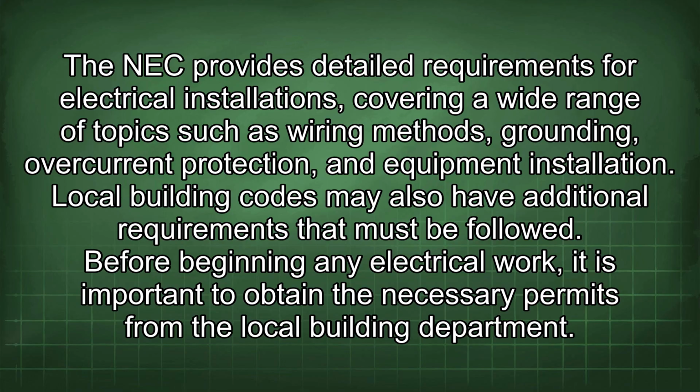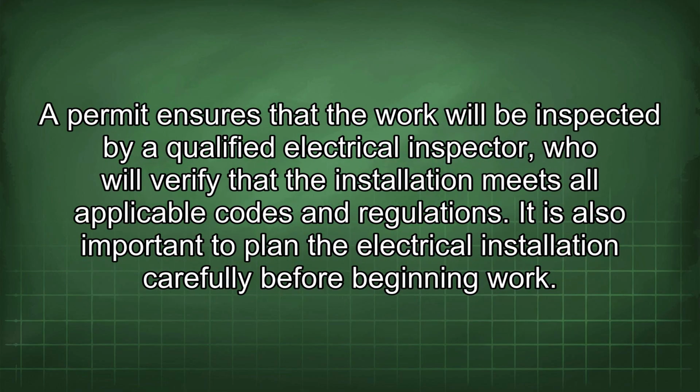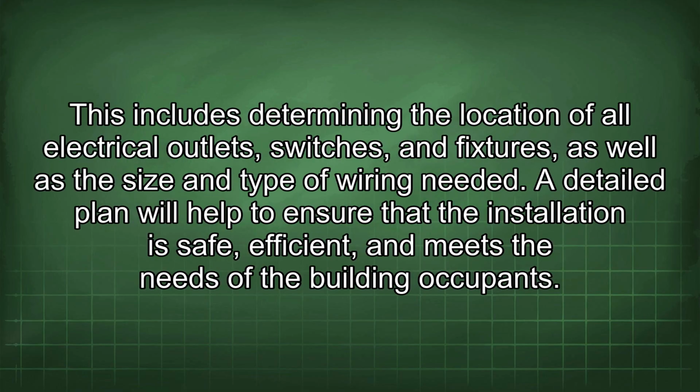Before beginning any electrical work, it is important to obtain the necessary permits from the local building department. A permit ensures that the work will be inspected by a qualified electrical inspector who will verify that the installation meets all applicable codes and regulations. It is also important to plan the electrical installation carefully before beginning work. This includes determining the location of all electrical outlets, switches, and fixtures, as well as the size and type of wiring needed. A detailed plan will help to ensure that the installation is safe, efficient, and meets the needs of